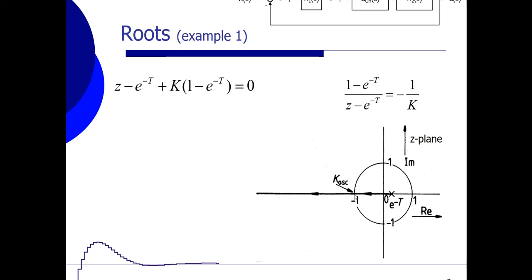And that instability point happens over here. When the pole is at -1, I'm just at the border of my unity circle, my system starts to oscillate and will not be stable anymore. So this is the boundary for stability.